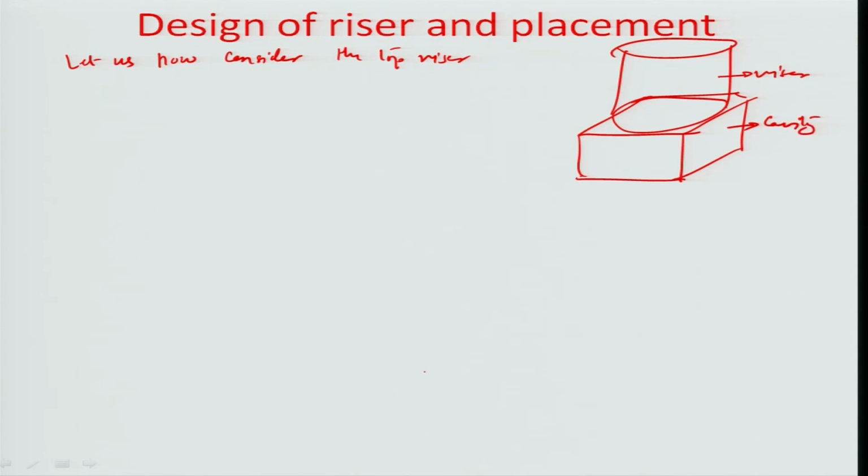Okay. So, now what effectively would happen is that the area of the riser becomes a little different. The area now becomes equal to only pi by 4 d square plus pi d h. Okay. That is the top area as well as the curved surface area, the other area being the same as the area of the top of the cast. So, it is a common face, and so we do not consider that as an area through which heat transfer would take place anymore.